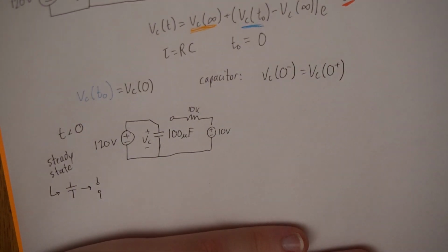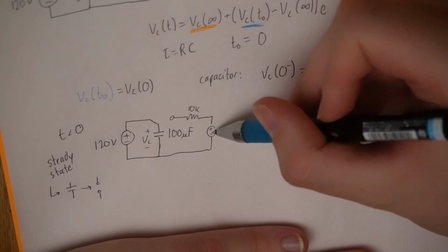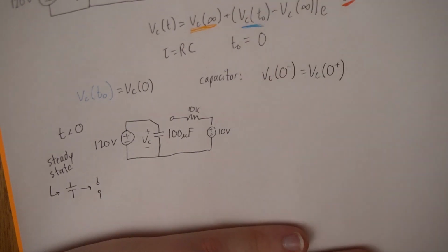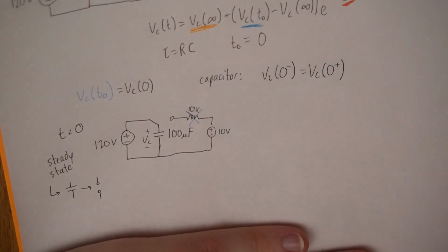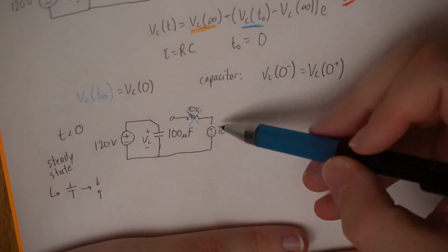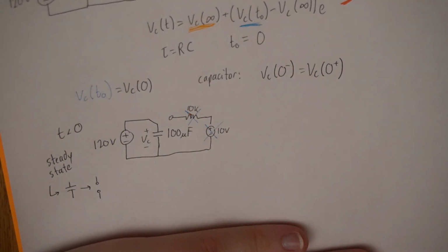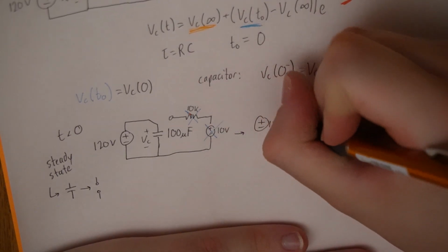Looking at this circuit, these two components, now it's great that they're there. No current flows through the resistor, so there's no voltage drop across it. And then the voltage source, we don't actually care about anything over here. I can remove that as well. So the result is I can redraw my circuit. It's even easier.